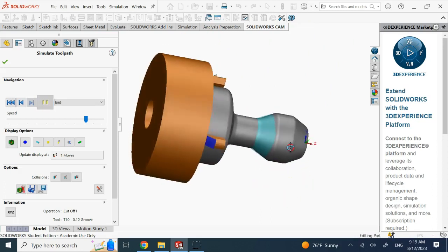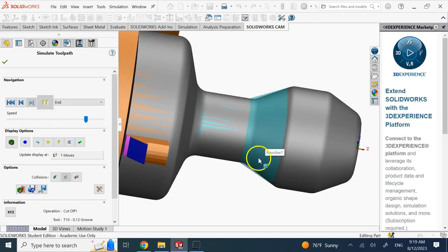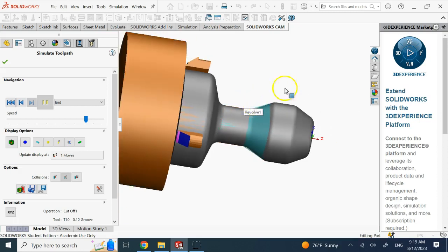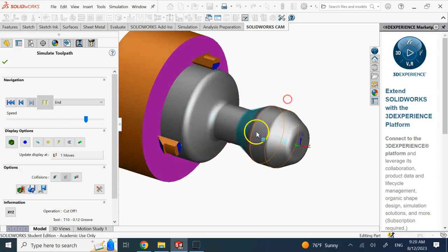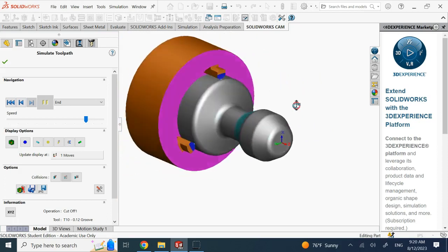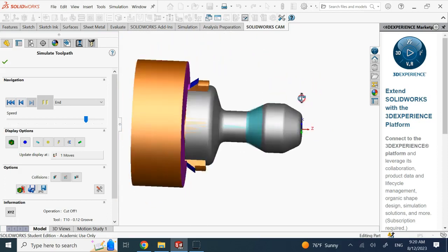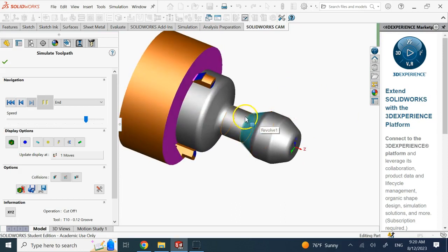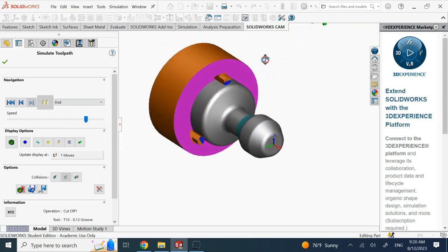And if you look here, that's interesting. This portion that you see is left in green. This is what the machine cannot cut. That is very important. This is a little bit steeper than the machine can really cut for you. So the machine cannot give you the perfect thing here. It is very close, but it's not perfect. So if you just have a lathe machine, you better change that angle here a little bit, make it smaller, so the machine can create the part for you.